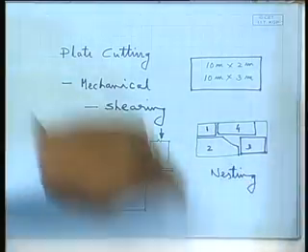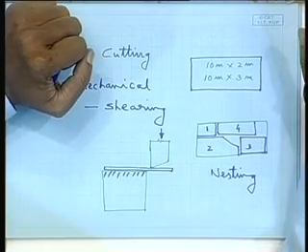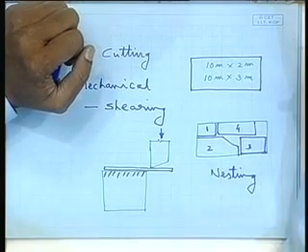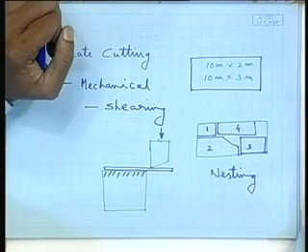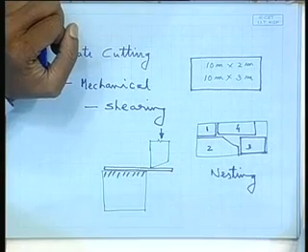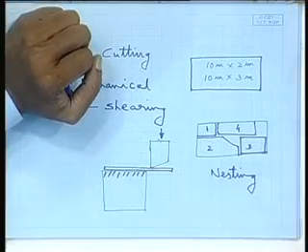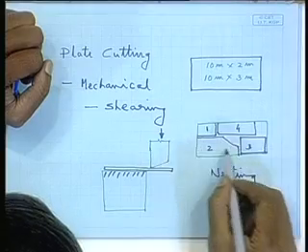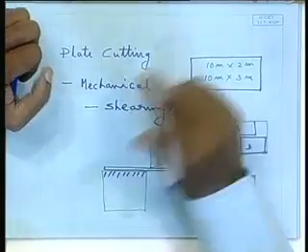This process of fitting the different shapes which need to be cut out from a 2-dimensional plate is called nesting. Now, with the help of your computer and available software, these operations have become very easy. You know the shape of all these once you have the design and the structural design done. So, you know what all kinds of pieces are needed. You have seen in our structural arrangement various sizes of brackets, various types of floors, shell plates, everything is needed.